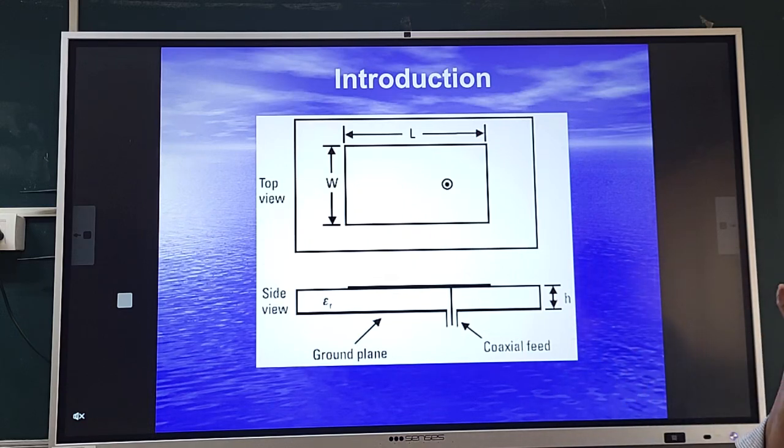But for proof-of-concept purposes, or if you want to design a low-cost solution, a glass epoxy substrate is definitely preferred. There are other ways of using the same FR4 substrate in an efficiency enhancement mode, that is the air suspended design, which I will tell you about in due course of time, because in most practical projects you are going to use FR4 in the air suspended mode.